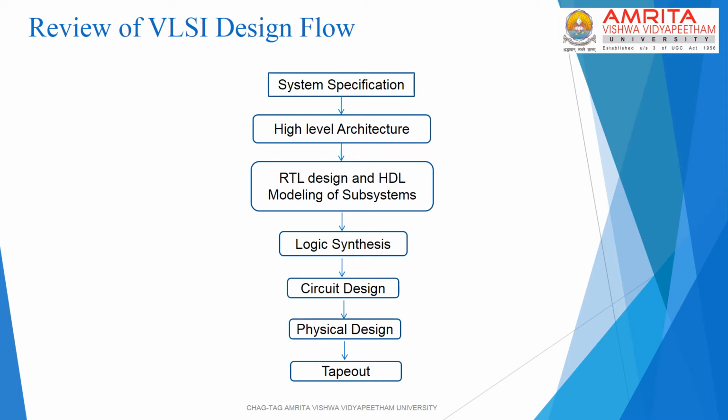And once the HDL modeling stage is over, the designs are synthesized using a synthesis software. And the outcome of the synthesis process will be a netlist which will contain all the gate level descriptions, all the gate level implementations of the design. And of course, there are a lot of subphases in the synthesis process, like the generic synthesis into a generic netlist, and the mapping process where the gates will be mapped onto the gates which are available in a library.